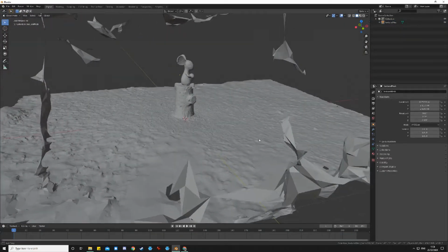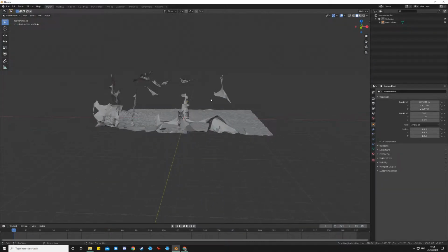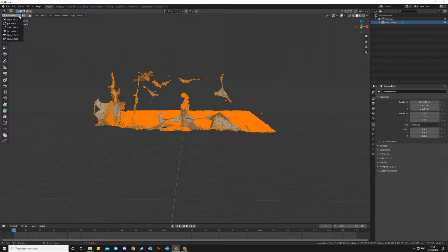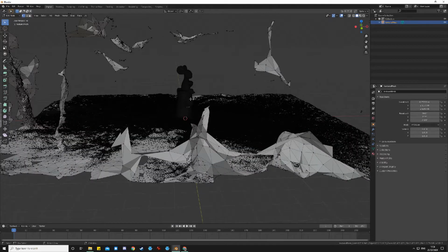I just need to get rid of the rest of this nonsense that's all around it. Usually I would go straight from above, but I'm going to have to remove this stuff at the top here just for that to work at all. So first of all, I select the whole mesh, and then I press Tab, and Tab puts me into edit mode. There's also a drop down box here. We were in object mode, but then we want to go into edit mode. Edit mode allows me to actually affect the vertices.